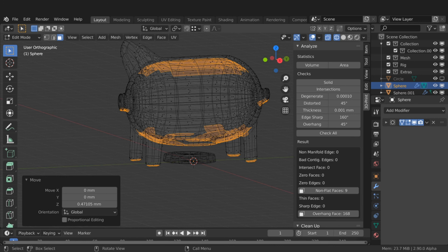The inner faces on the top are also overhanging and may be an issue. We can increase the detail of the print and this may help. You can also slow the print speed down to help reduce the risk of failure and make sure the material cools and stays in position.